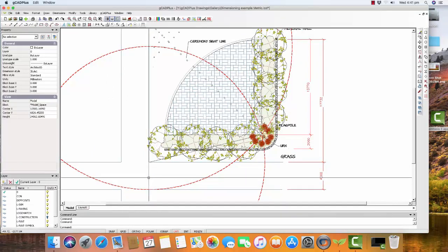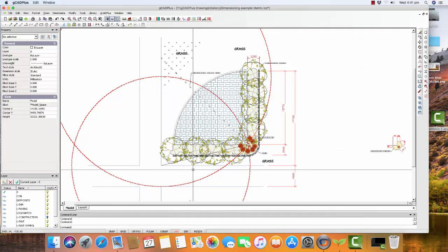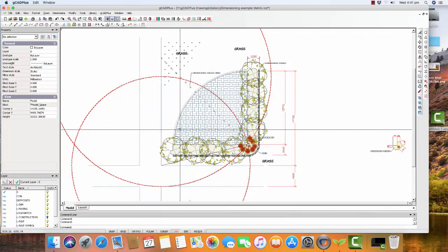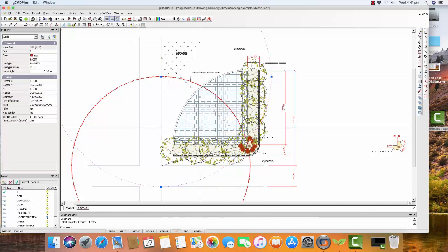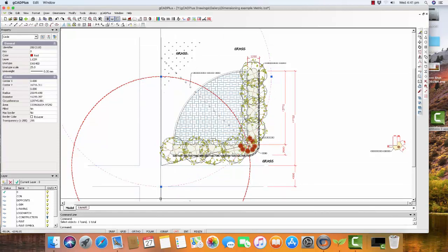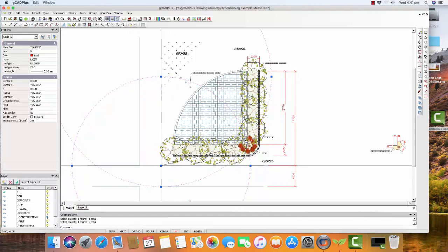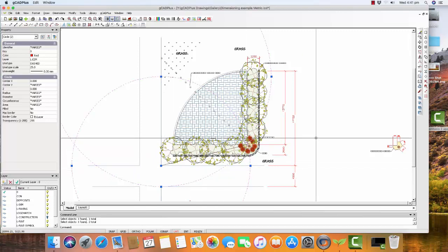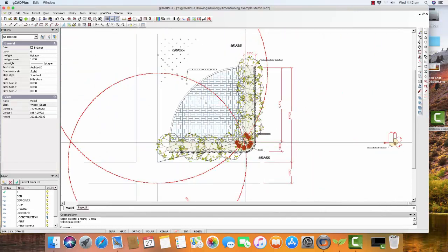There was an existing path running through here through an intersection, and what he did was to firstly determine the edge of the paved area, and that's determined by the intersection of two circles. If I click on the uppermost circle first, you can see its anchor point, or its set out point, is the corner of the path. And if I pick the other circle, the set out point, the center of this circle, is at the opposite intersection of the paths. So the point, let me unselect all, the point of intersection here gives the construction team